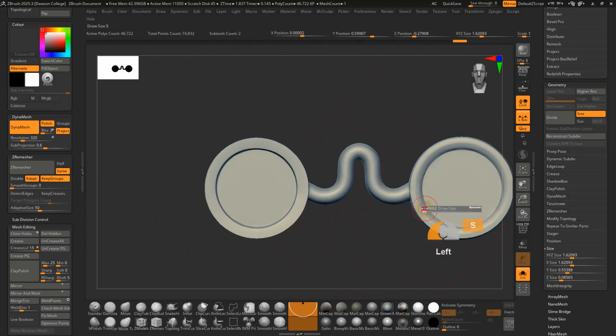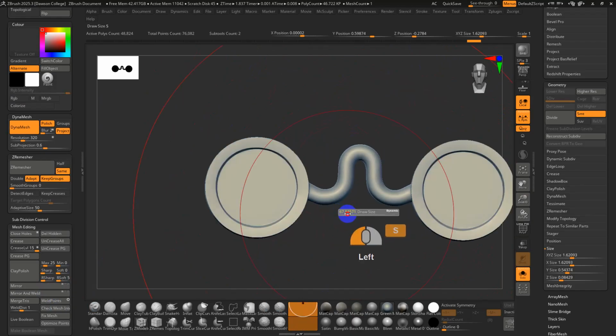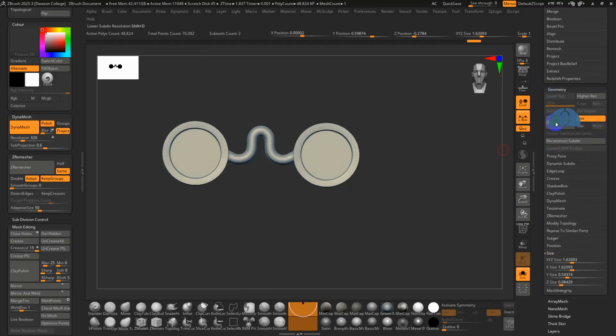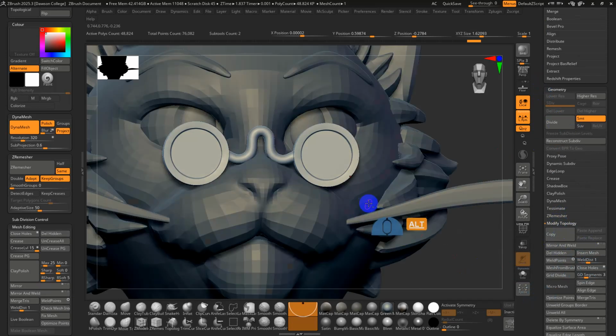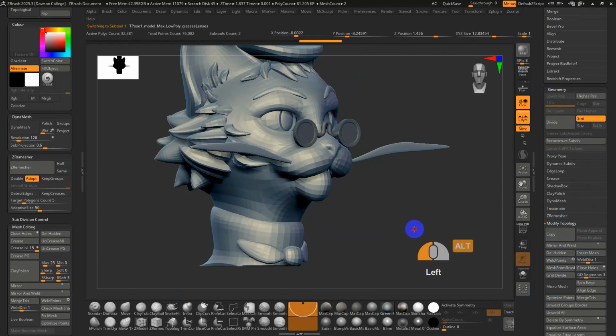non-deformed mesh. And again, I didn't do my mirror and weld yet, so I'm going to do that right now, mirror and weld, and you see I get the exact same shape now on both sides, right? So mirror and weld helps. Again, that's under geometry, modified topology, I believe, modified topology, mirror and weld, okay? Okay, so I'm going to go through these other tools.